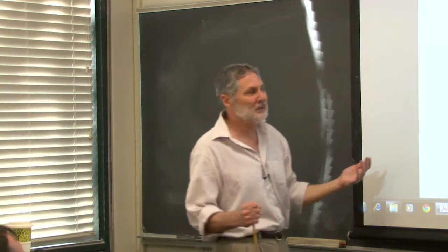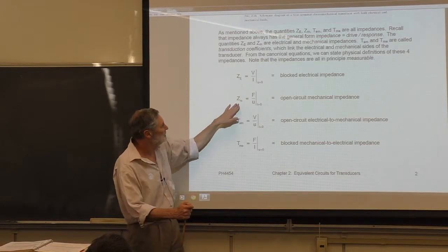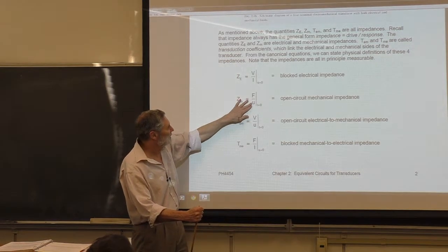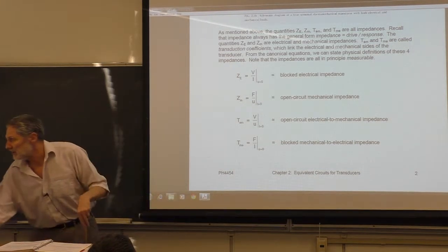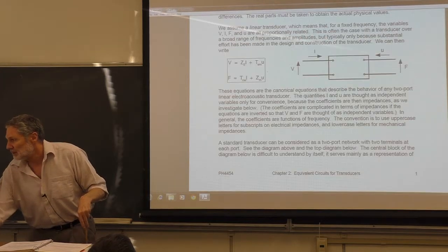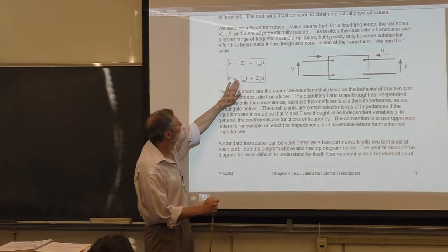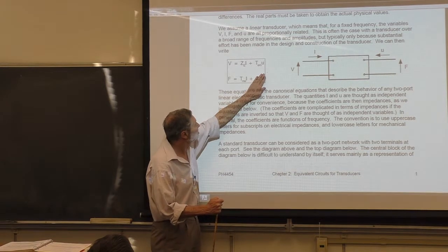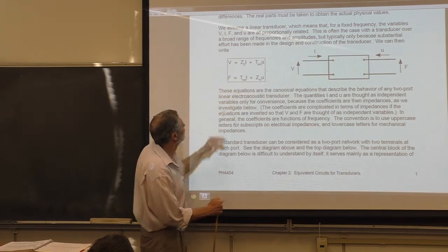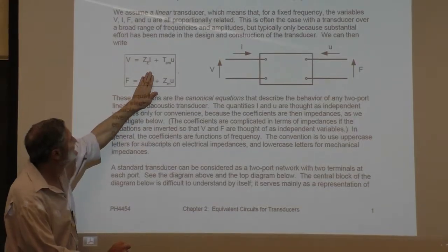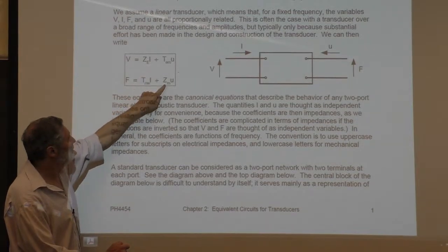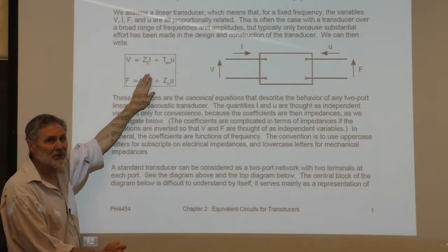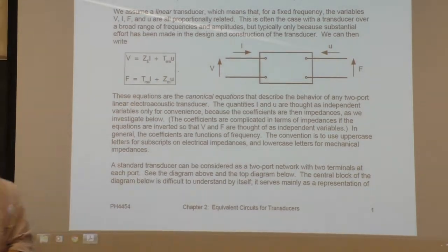And the mechanical impedance, very similar, right? It's going to be symmetric here. The mechanical impedance is the force divided by the velocity, and that's for no current. And again, you can check this. You look at this equation. When we have no current, then the meaning of this impedance here is the pure mechanical impedance, the force divided by the velocity.